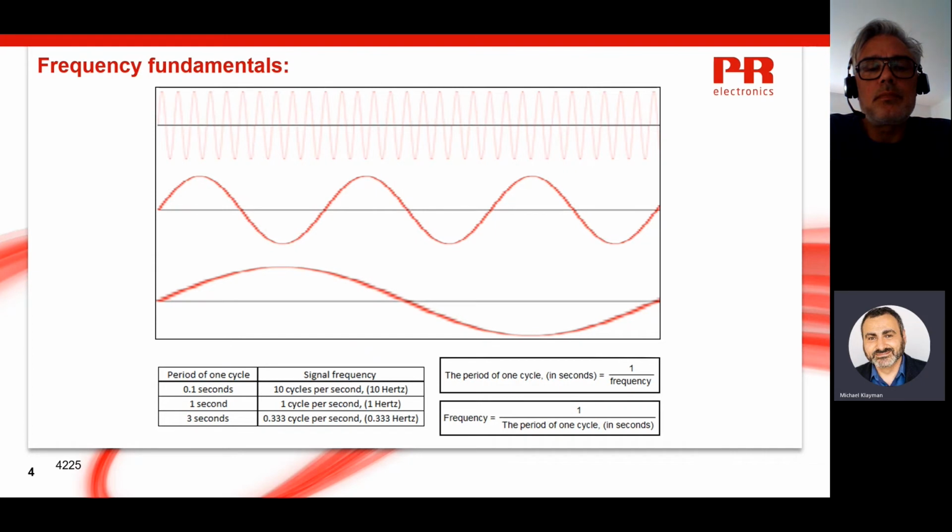If the signal repeats at the same rate of once per second continuously, you can say that the signal is changing at a frequency of 1 cycle per second. Another way to say this is that if you pick a point in this cycle, the positive 10 volt peak, for example, as the signal changes in voltage level, you will see that peak again happen in the next cycle in 1 second. That plus 10 volt peak happens at a frequency of once per second.